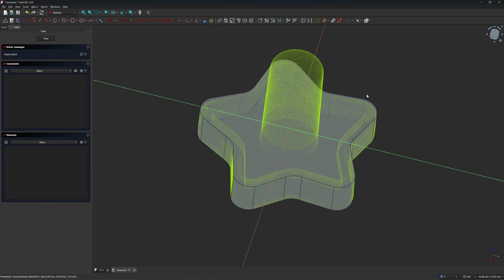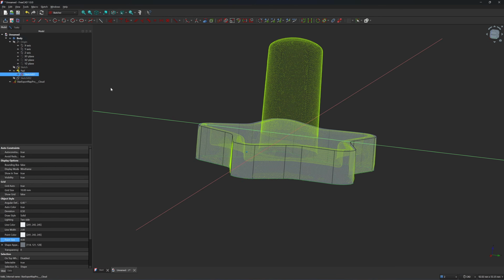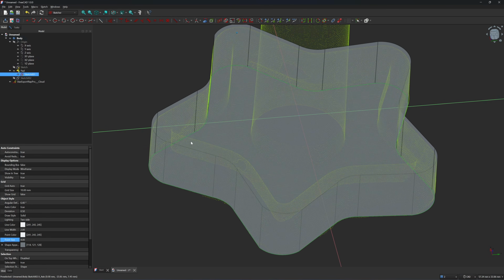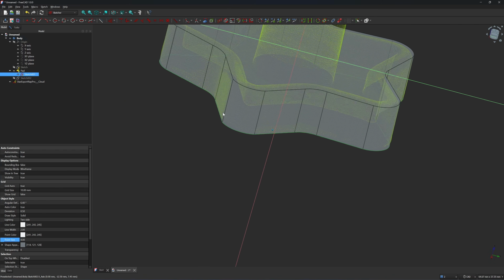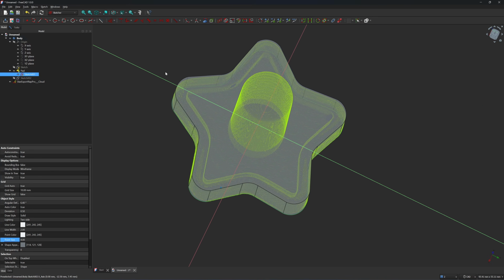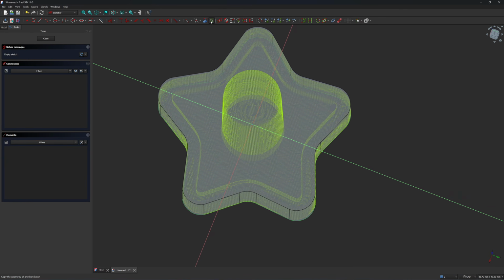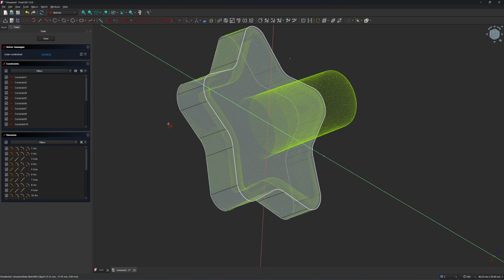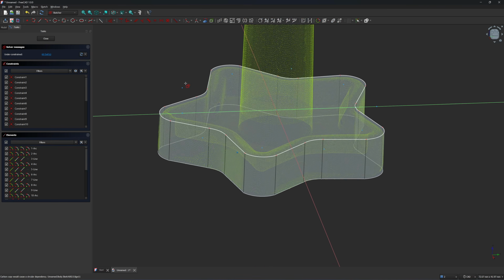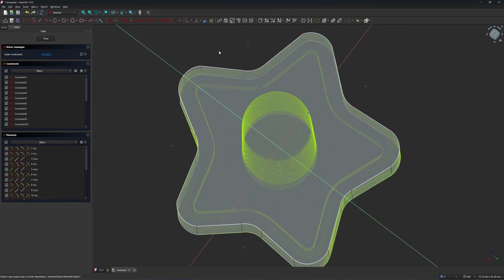We have a sketch. I'm going to go back to the model and turn on visibility for the first sketch that we just made, because I'm going to copy the first sketch to this one here, to the new sketch. So what I do is that I'm going to click on this command, create carbon copy. So create carbon copy of this sketch. Okay, the first sketch is now on the top here, and next I'm going to offset the wall thickness.